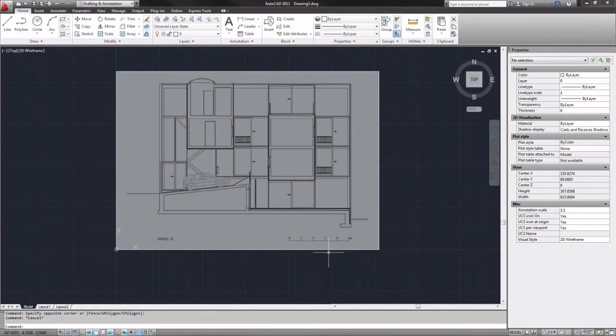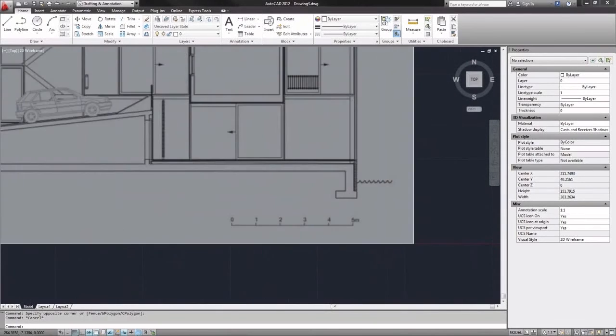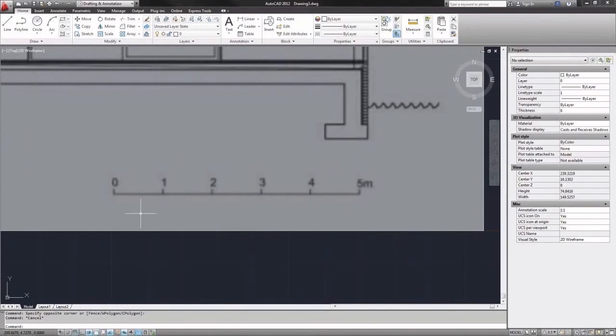So next we will try to figure out how big this image is. We can use this scale here in the bottom of the image. We can go ahead and measure it, typing distance, and click one end of the scale, and then click near the other end of the scale, and that says 69.2 millimeters.